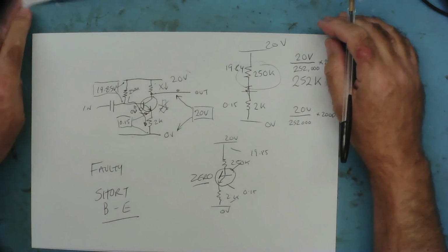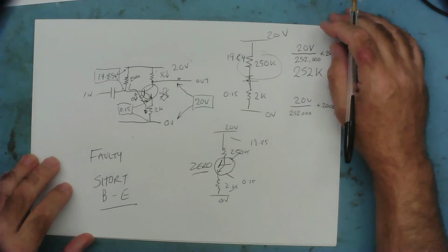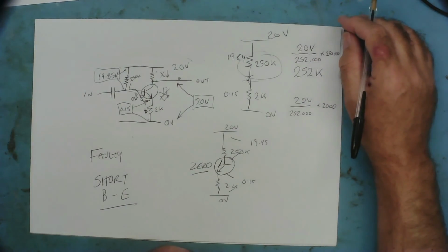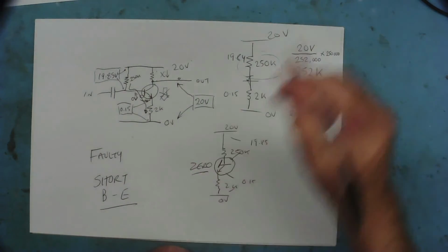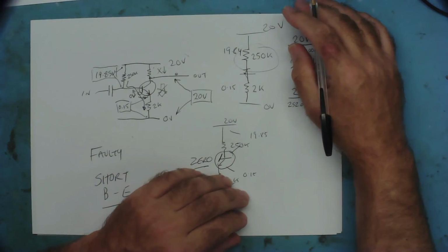You'll say, what's the point? Well, the point is just to prove you understood it properly, yeah? Get your meter out and get on the resistance or diode range and go find the short circuit. Okay guys, hope you like that, and hope you enjoyed that.